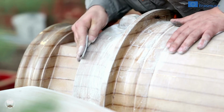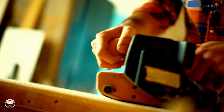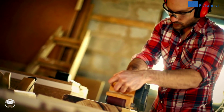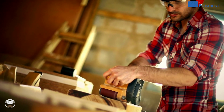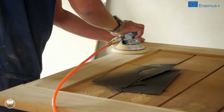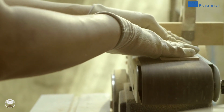The first step to obtain a good result in a process of wood painting or varnishing is the sanding process. If proper sanding is not performed, the end result will not be as expected and will be well below the expected quality. There are several ways to sand wood, including manual and automated sanding processes.